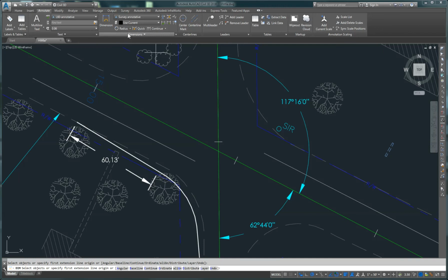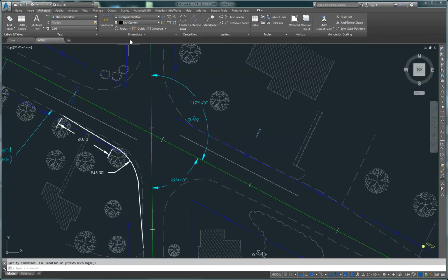To do the dimension on the radiuses all the way around, the radii, you come over here, click the radius tool, again under dimensions, get a drop down box, pick radius. Under there we go. You'll click the arc and then just back it up. It automatically drops in the dimension for you. And then you can also use this and say that you want the aligned command. Again, we're going to make sure we get the end point of the arc to the end point of that and pull it out.